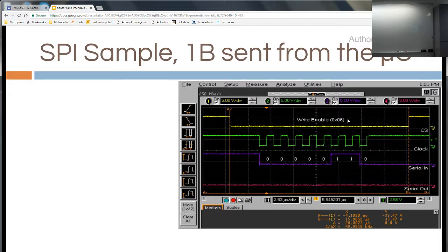Why is there write enable? In addition to this, wait a minute. This signal is not correct. The clock and serial lines are okay, but there's no write enable. There's a chip select. Chip select. I see. The write enable actually means those bits here, 06 hex.